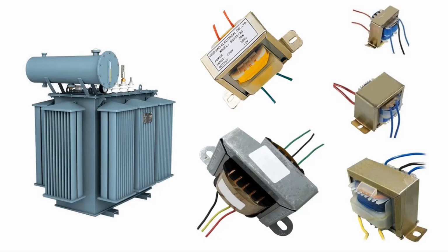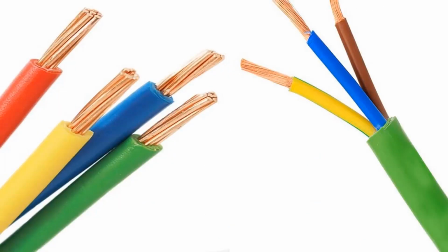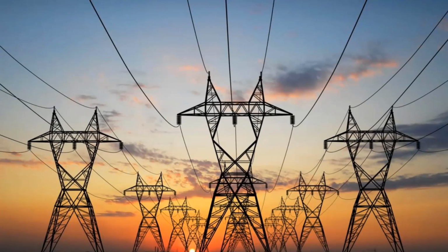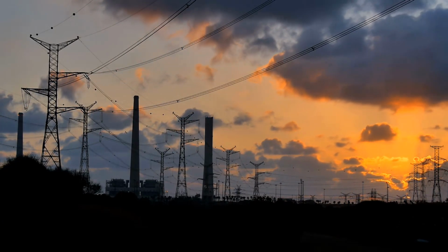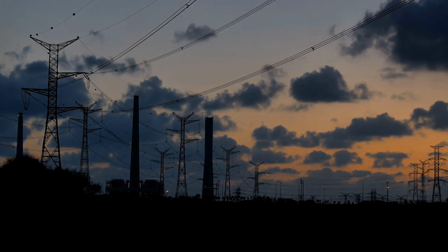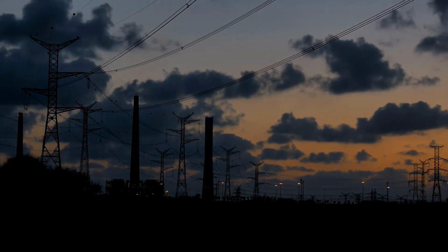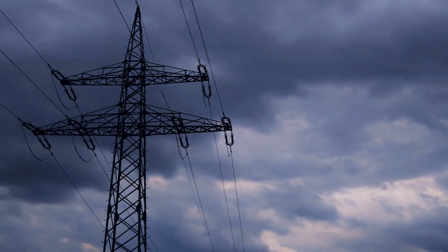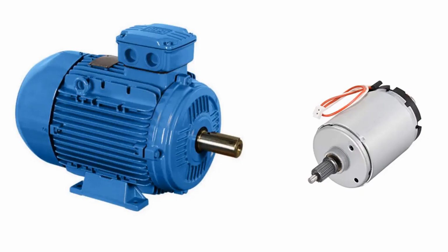It's obligatory to use thick section cables in the distribution of this obtained direct current to the receivers. But since the voltage value is high in AC, the current value is very low compared to direct current. For this reason, thin section cables are used in AC networks compared to DC. If the electricity carried from the power plant to the cities was not AC but DC, these cables would have been much thicker rather than thin like this. Because we can easily convert AC to high voltages with transformers and carry it with thinner cables. But very high voltages are difficult to achieve with DC.